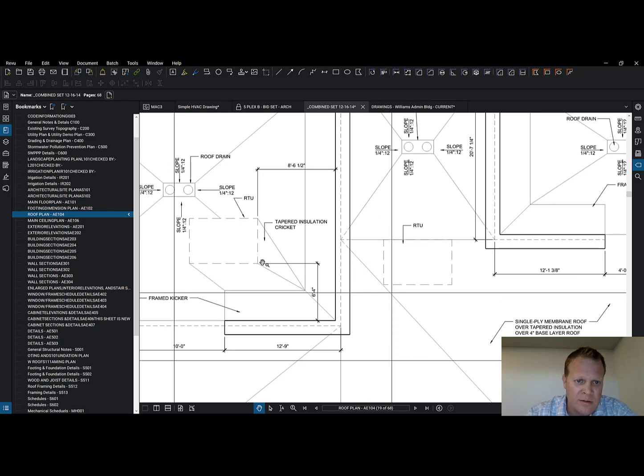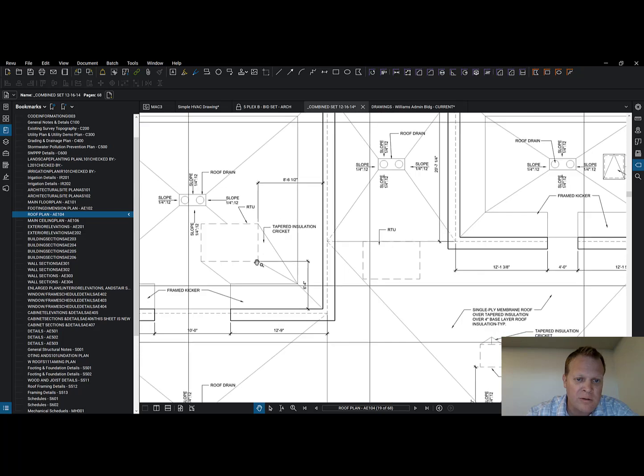But sometimes they don't, and they miss it, and it's up to the general contractor to coordinate that. But what we need to pay attention to is the roof curb height. If we have a pretty big tapered insulation cricket that's built out so that the water will flow this way and that way, and it goes up pretty high, some of them can be pretty big, and it would be a bad day if we didn't have enough room from the top of the roof to the openings of the rooftop unit to get the cricket in. Anyway, the cricket is something to pay attention to.